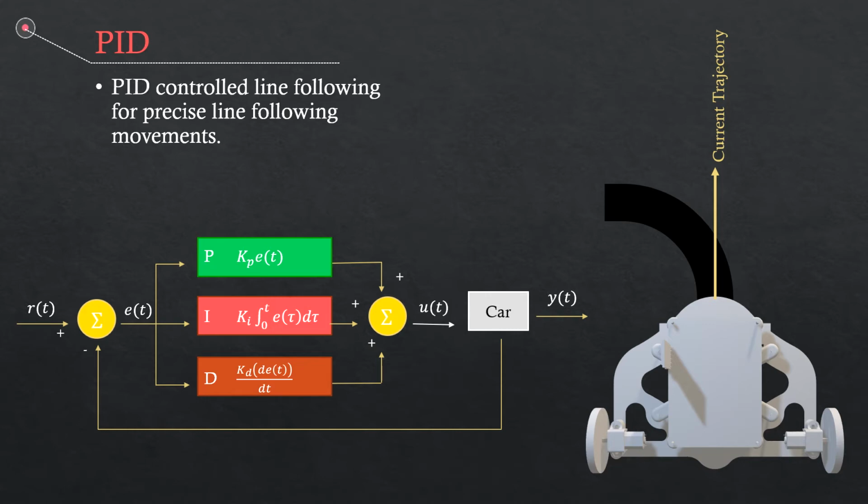To adjust, the PID controller had a proportional term Kp, which proportionally varied the steering angle based on the current error. Proportionally controlling a car's steering angle with sharp turns, however, could lead to an oscillation state, which can be accounted for by predicting the next steering angle, the derivative term Kd, and accounting for it at the current state.